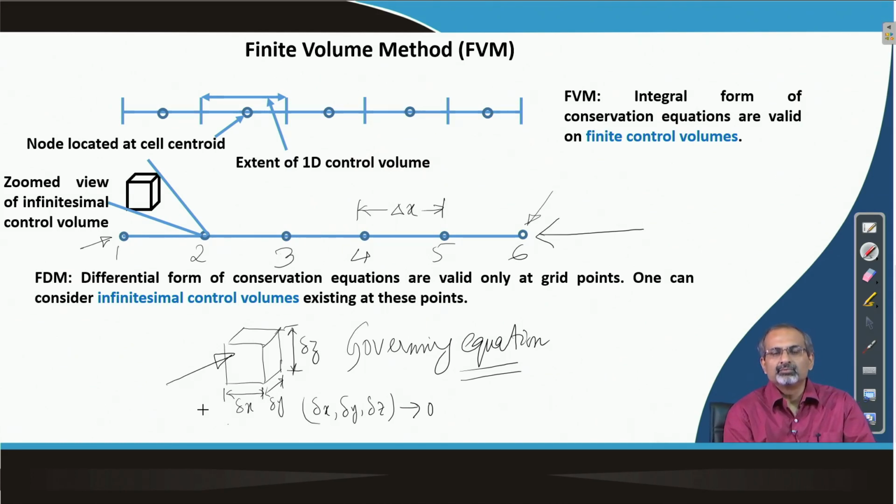Now, the moment we try to approximate the governing equations, we are introducing different errors in approximating them. The first error that we commit when we have a finite number of grids to represent the domain is that we try exactly satisfying the governing equation only at a few discrete points and nowhere else in the domain.